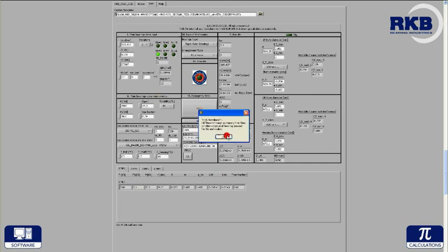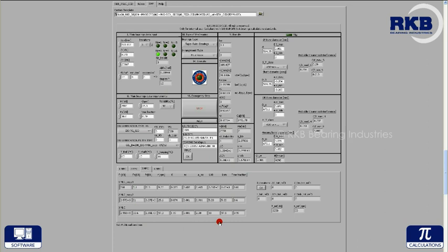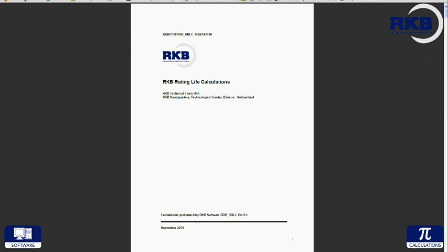After each iteration is analyzed and information stored in the data review table, the software applies and solves the intermediate step related to the variable load conditions, displaying the basic radial life and modified rating life for the studied case. The results are exported as a data report, containing all the iterations and computational information.